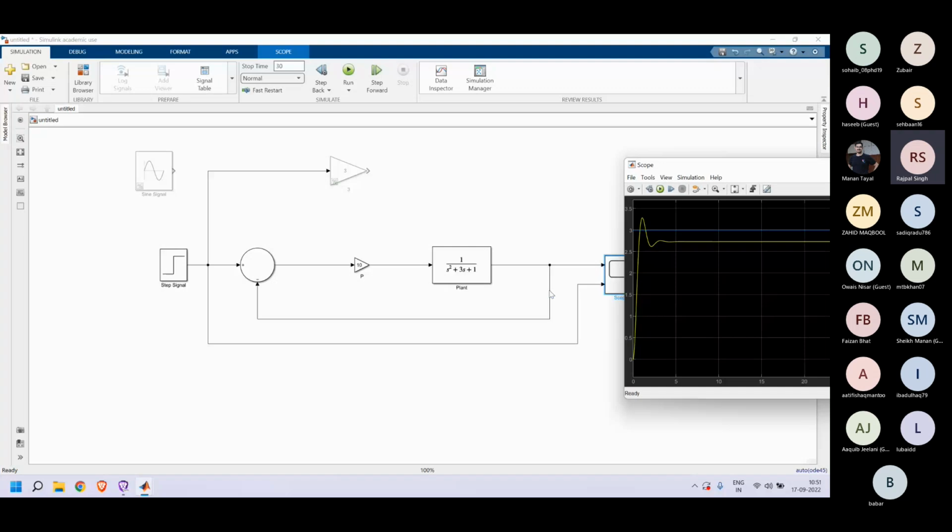And that's because it doesn't have a pole at 0, so its error won't completely vanish. Unless we introduce an integral controller, we'll have to increase gains to really large values and introduce really large oscillations if we want to get the steady state error to really minimal values, but it still won't vanish completely. If you have an open loop first or second order system, it will have a zero steady state error. Yes, sir.